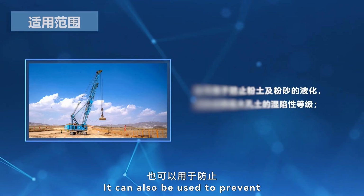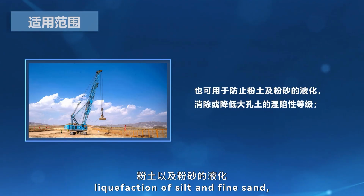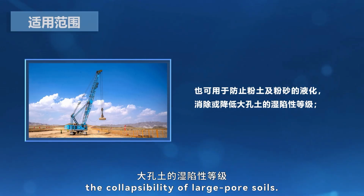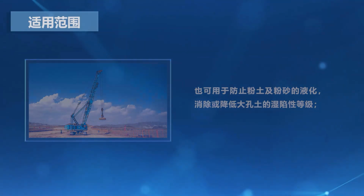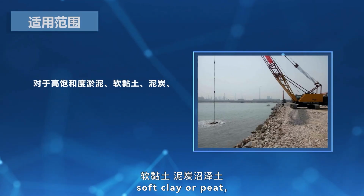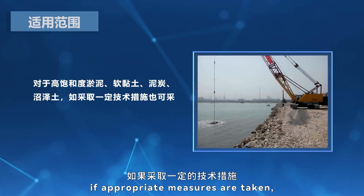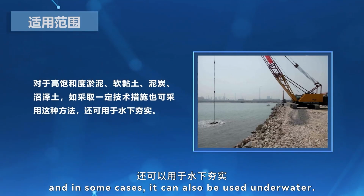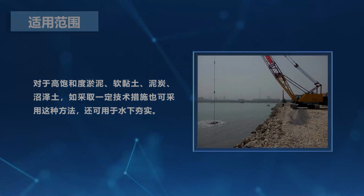It can also be used to prevent liquefaction of silt and fine sand, and to eliminate or reduce the collapsibility of large pore soils. Even for highly saturated sludge, soft clay, or peat, if appropriate measures are taken, this method can still be applied, and in some cases, it can also be used underwater.